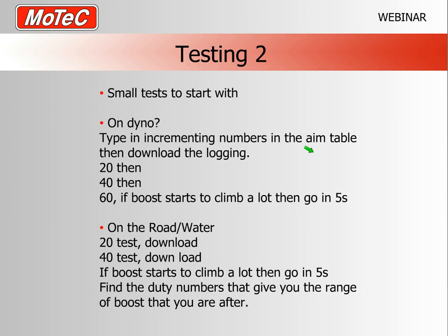Second part about testing, we just need to do small tests to start with because of the fear of overboost. On a dyno, we type in the numbers as it says there, and if you're testing on the road or on the water or something like that, type in a very low number to start with and get an idea of what's going on. Increase the number, the boost should go up. If it doesn't, go back to your setup.